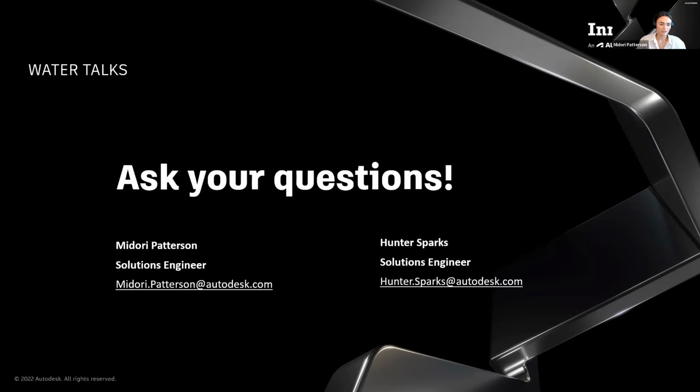And I'm not sure, Thierry, maybe if you want to provide a little more of what you're looking for in analyzing watersheds or subcatchments. There's definitely, within the inflow areas in InfoDrainage, different parameters that you can add about imperviousness levels. But as far as analyzing those subcatchments, there's also no way to automate those subcatchment delineations, if that's what you're asking for.